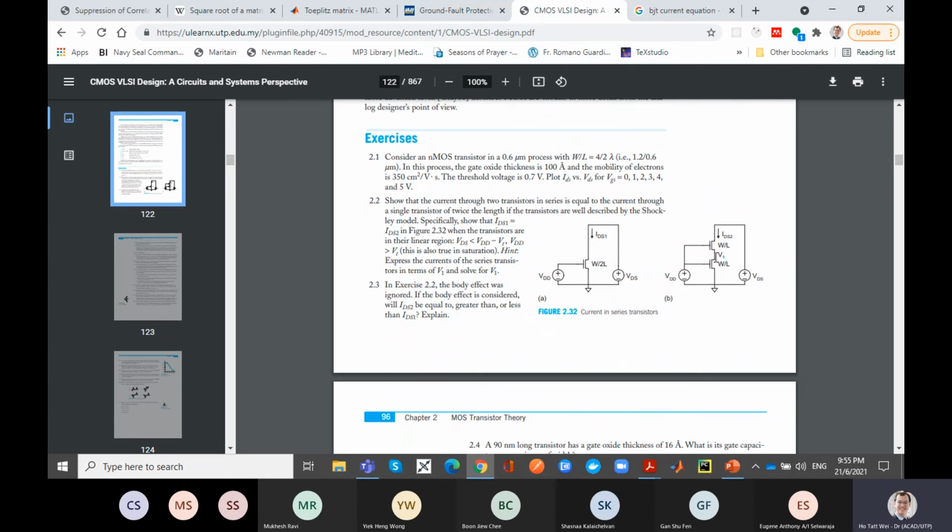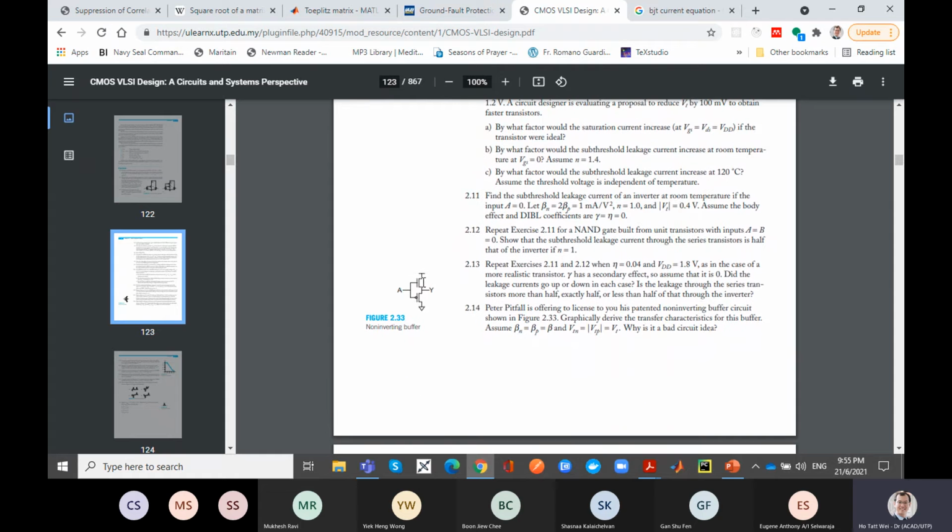Whereas if you look at this kind of gate here, VGS is here. If you turn this on, it's going to go to logic 0. So this node is changing, the voltage here is going to go down, but VGS is always fixed. It's consistent throughout the operation of the gate, which means the conductive channel that is formed there always guarantees that number of electrons. So the current is always available and consistent. This is the point I wanted to highlight to you when you are studying this. Okay, Eugene, can?